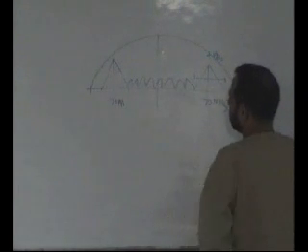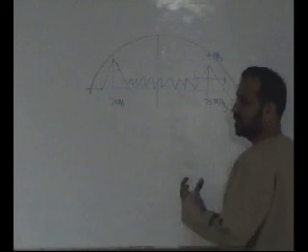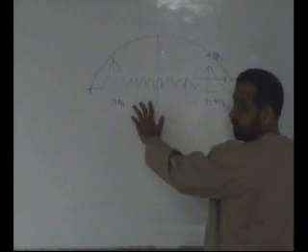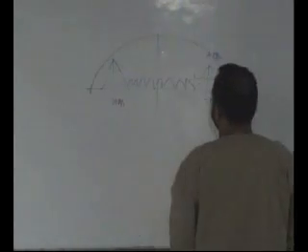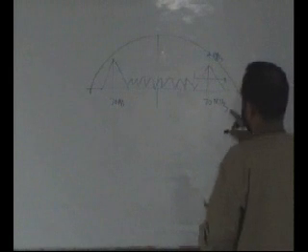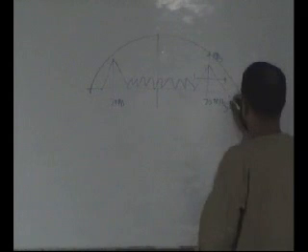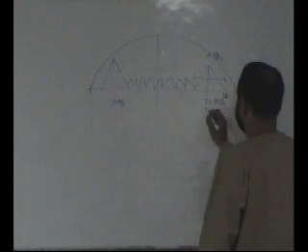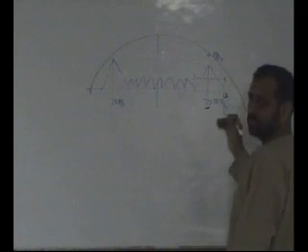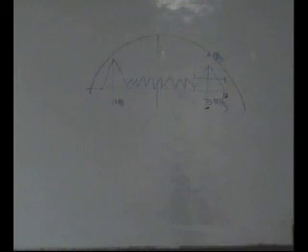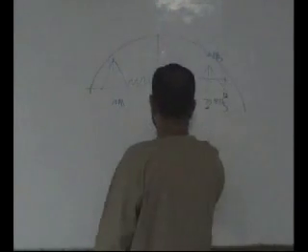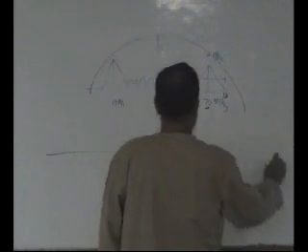If this is the case, then you don't use band pass sampling, because this spectrum is not clean, but the rest of the spectrum is clean. So it's better that you sample it at what rate? So this is 72. By the way, 70 megahertz is the standard IF. It is used almost in all digital receivers, 70 megahertz or 21.4 megahertz. So you sample it at 144 megahertz. Once you sample it at 144 megahertz, this is what you get.